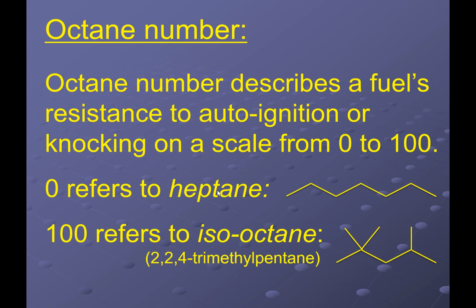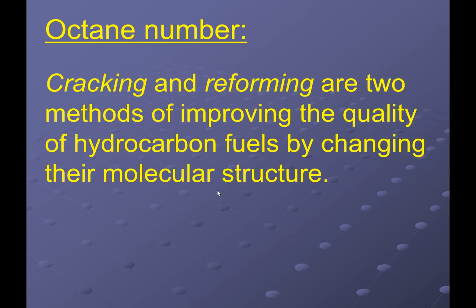I'm just going to show you one other slide here. Remember, out of fractional distillation, out of this natural boiling point tendency and condensing at different layers, we don't tend to produce a lot of the C5s to C10s that we want for fuels. What we can do chemically is a reaction called the cracking process. Cracking involves changing things that are too heavy or too light into the ideal C5s to C10s. So this is just introducing the terminology. We're going to see this much more in the next lesson. Cracking and reforming are 2 ways I can improve the octane rating of my fuel.